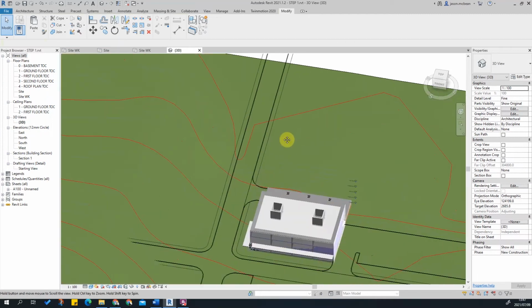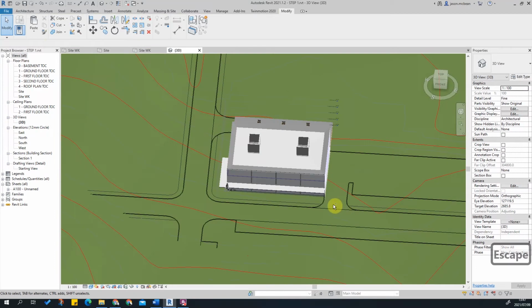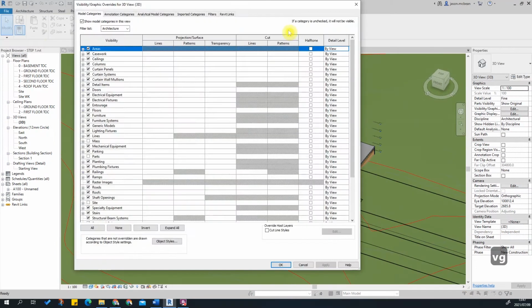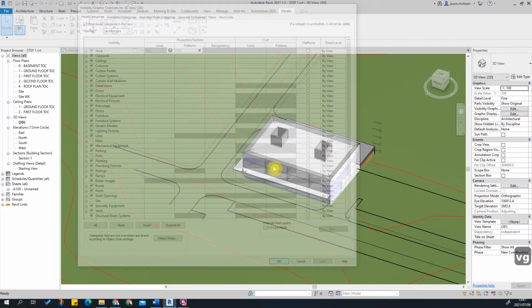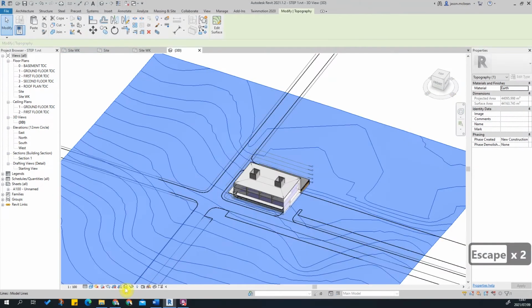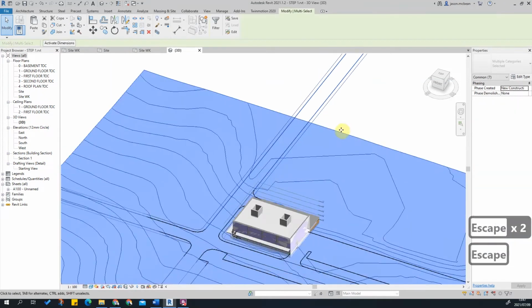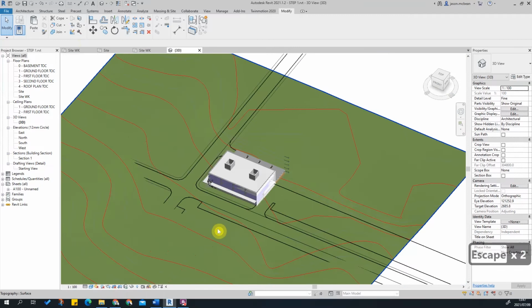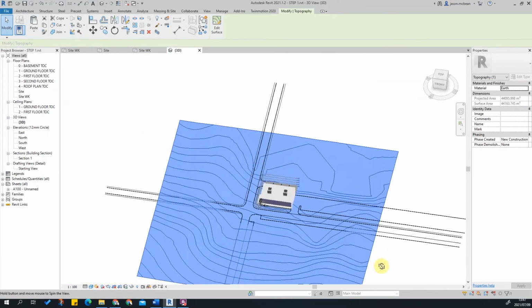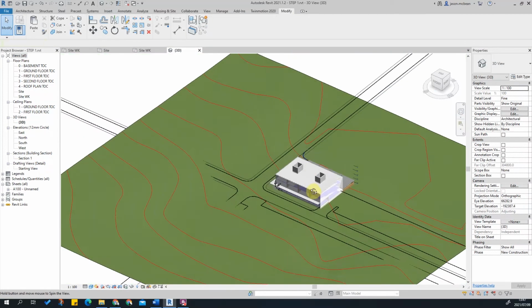Okay, the next thing I need to do is split the surfaces up, so where the parking is going to occur and all of those. So for now, I'm just going to switch off all the model items, that's totally up to you. But for example, I can just click isolate. So select all of the line work maybe. You could select all this information, but ultimately all I need is the line work to help me cut out the road network on this topography. We use this in combination, especially later on if you want to export this to 3D view.